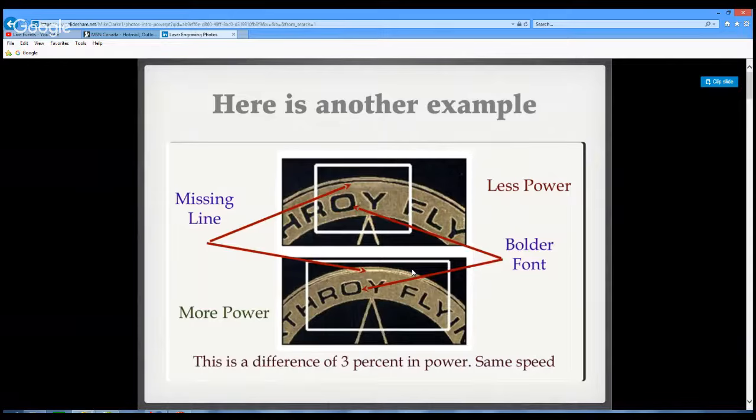There's never really a golden rule because certain wood is better with a certain power, and another wood might not be as good with that same power. So you might find a pine generates a more brown image, so you might not need as much power on that because you get a darker, good contrast image, versus maybe a maple image that doesn't generate as much of a brown background.